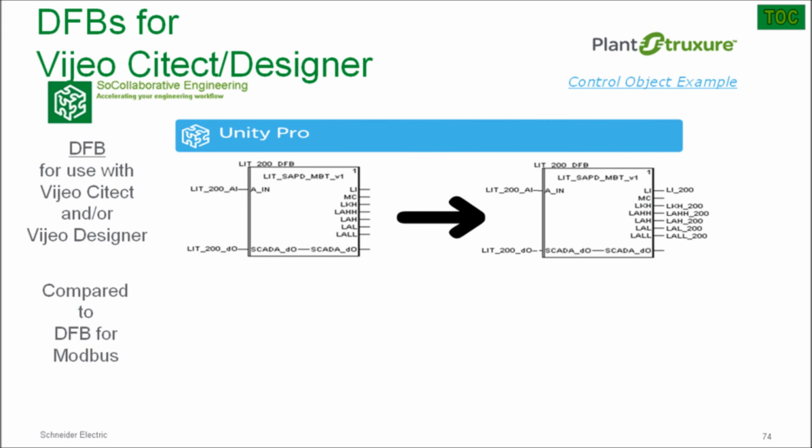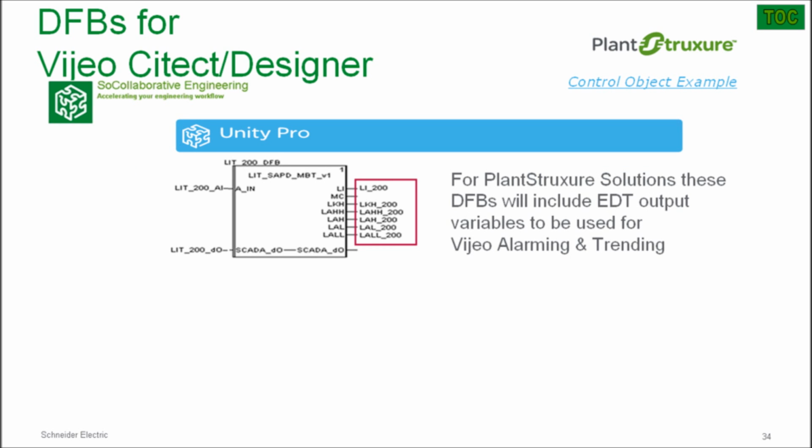Now that the inclusion of these variables is a non-issue, why are they included or necessary? The ability to apply Unity Pro variable custom field content is only unrestricted with elementary data type variables, and these variables will have the U2V syntax VJA and VJT applied to them to identify them as alarm and trend tags in Vijeo Citect, which in the grander scheme will further optimize this DFB into the total solution. More on the U2V syntax to come.